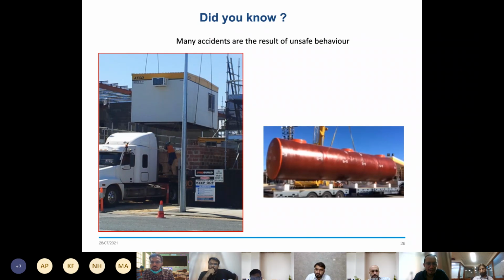But it is just for a while, just a 2 or 3 minute job. He just goes up, hooks the tackles, and then comes down. All right, but there is no PFA and no fall protection barriers there. To be honest, if you look at the right process, you need to erect your scaffold and then make a proper walking platform on top. So it might take you around 1 hour plus to prepare all the necessary controls just to unhook the sling. Exactly.